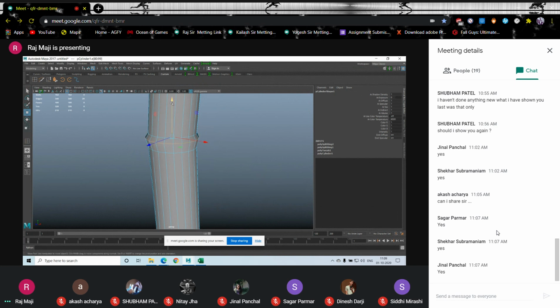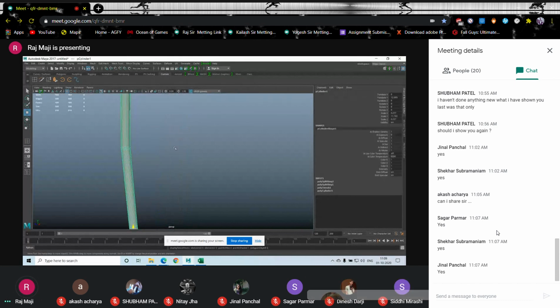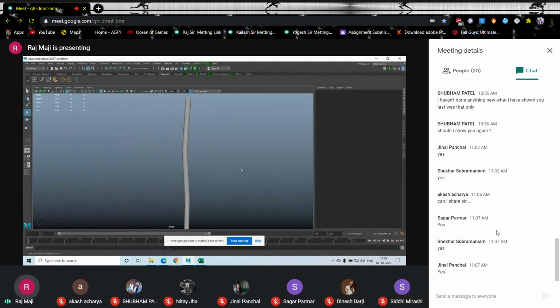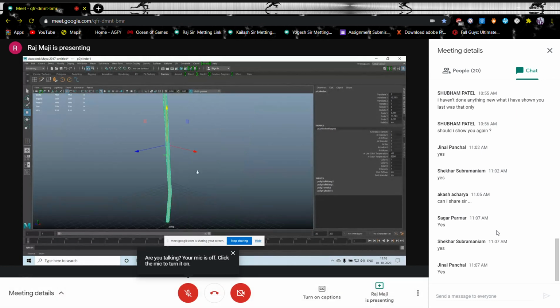After pressing 3, that knot will be visible. I can exaggerate it a little bit more. In 1, it was looking fine. Now the problem is, in these sides I have used 20 divisions, and that was the first mistake. Akash, in your case also, this is the reason.